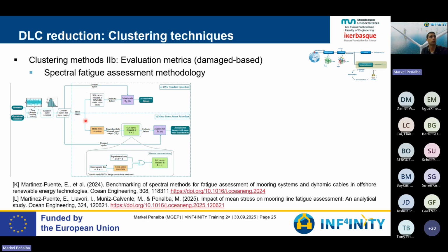time domain technique. So basically what we do is we extract the tension time series results of, in this case, the mooring lines, but it could be any other component, for the different environmental conditions we want to analyze, either with or without clustering techniques.